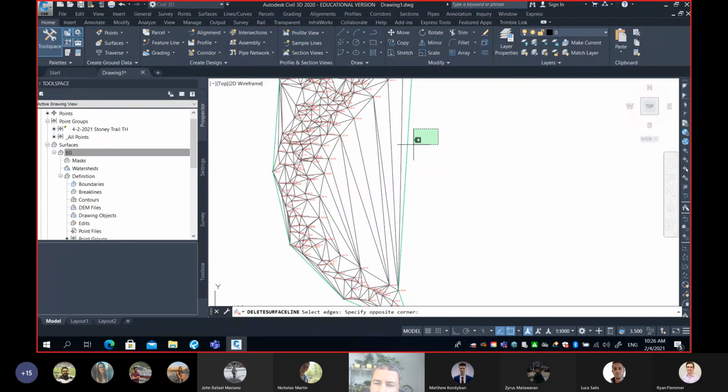In AutoCAD, once you draw anything from right to left, like so, you can see the change. This one is left to right, and this one is right to left. You guys know that this is called crossing. So all you have to do is you can do this. You can see I'm just moving, and if I keep going, probably it will remove one good triangle. So I'm going to go back a little bit.